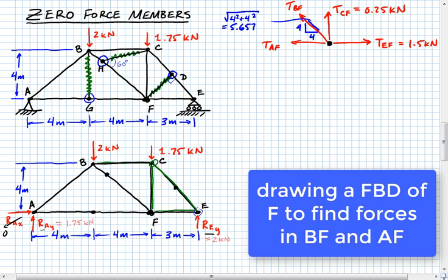equations on this. The thing to notice here is that we have these two forces, TBF and TCF, acting in this vertical direction, and we know TCF, we don't know TBF. If we do the vertical direction first, summing forces in the y, then what we'll find is that we'll only have one unknown variable in that equation. All right, so here we'll do that.